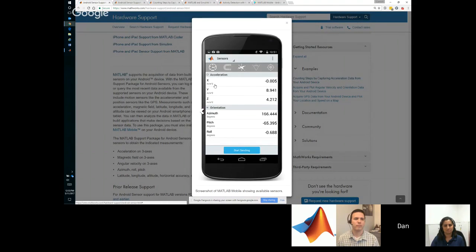And in her demo, she actually controlled all of this sensor acquisition from within MATLAB. So she did m equals mobiledev and m.Logging equals 1, m.Logging equals 0, m.AccelerationSensorEnabled equals 1. So that's a really cool way to do it if you want to do everything controlled from your computer, and maybe the phone has to be in a certain place and you can't be touching the app.